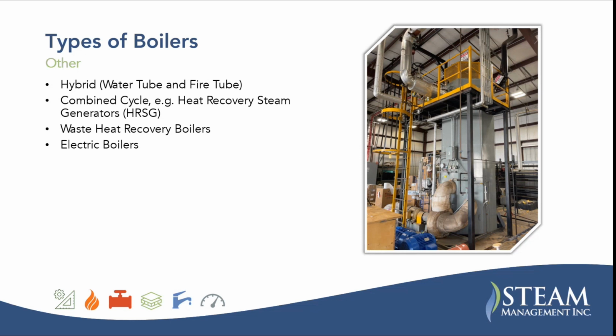How do you measure the combustion efficiency of the condensing boiler? I think it's still the same kind of method. There's definitely testing procedures to do that. If I was doing it or trying to estimate it, I'm still looking at flue gas temperatures and kind of what I described before. So your flue gas temperature is going to get much lower, and then you're going to have to calculate how much of that is water and how much latent heat is being taken out of that as well.